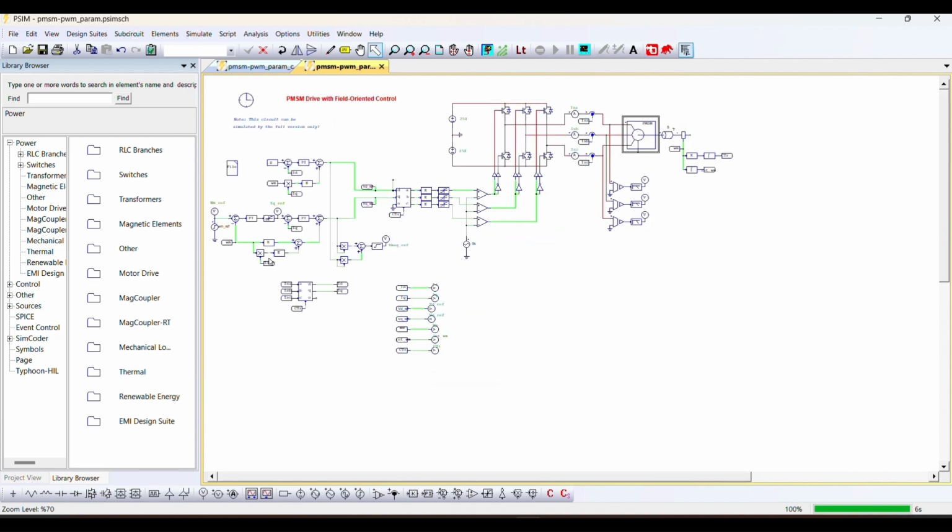So the important part here is calculating the speed of the motor, based on which the rest of the calculations proceed. For that, we are using a sensor in the motor, which will sense the speed and send the data to the control part here. Accordingly the process takes place and the control of the PMSM motor is achieved. So this is the traditional way of doing it.